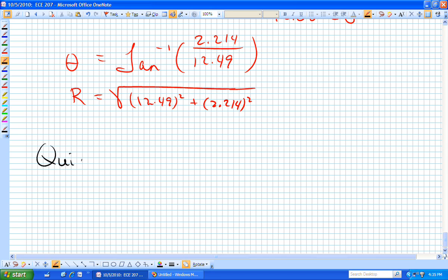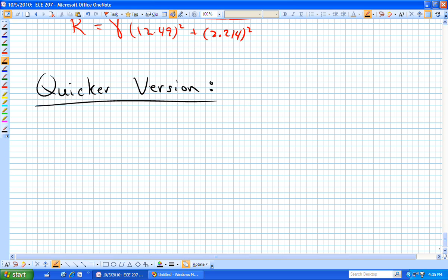And what we're trying to do is get comfortable with this process or concept so that we can do this rather quickly and we can do the algebra instead of having to worry about derivatives or these differential equations with sines and cosines, because that gets kind of tedious, trying to solve differential equations with cosine and sine forcing functions. Now we can just put them into the phasor form, do our algebra with complex numbers, and if we want, we can pull those back into the time domain at the very end. Is that making any sense?